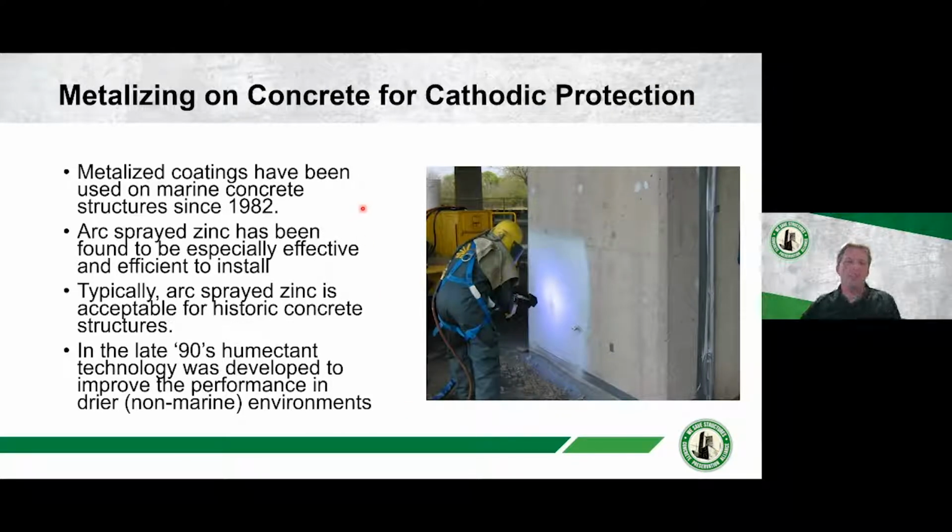Metallized coatings have been used on marine concrete since 1982. Arc sprayed zinc has been found to be effective and efficient to install. It works very well in overhead situations, so bridge deck soffits, parking structures, those types of areas, and it can accommodate some different geometry. It is used at times for historic concrete structures because of its color and appearance.